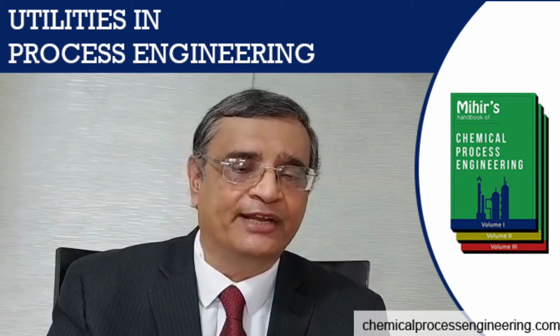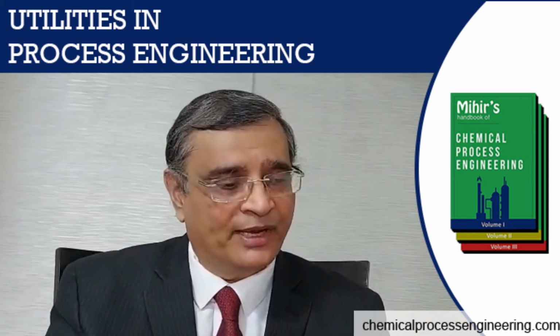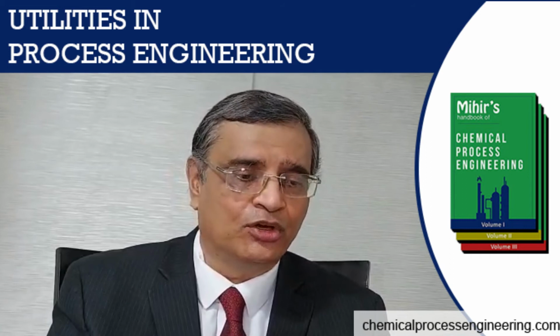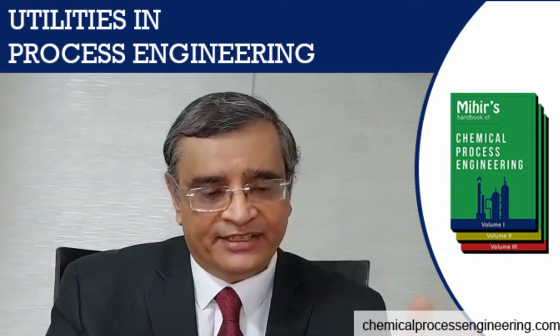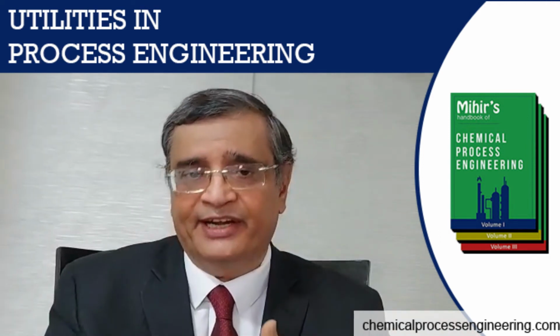For example, you start out with the compressors. Mostly screw compressors are required here, oil-free screw compressors, although small plants may use reciprocating compressors also. Then you have a wet air receiver, which is roughly 3 to 5 minutes of throughput storage capacity. Then you have the air dryers. Many types of air dryers are there.